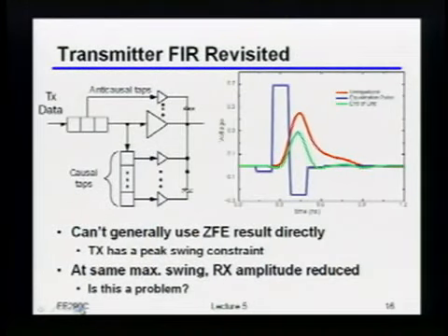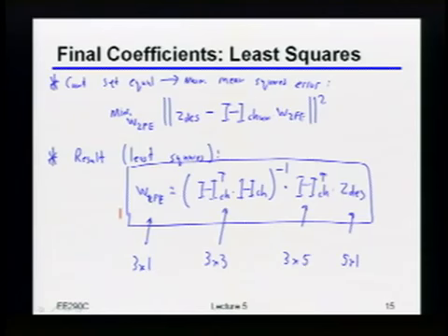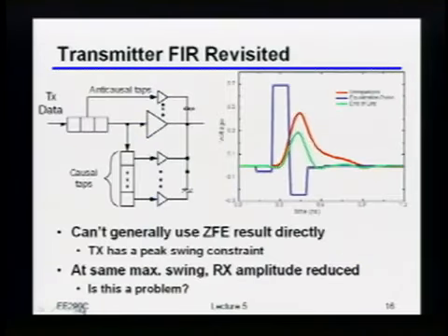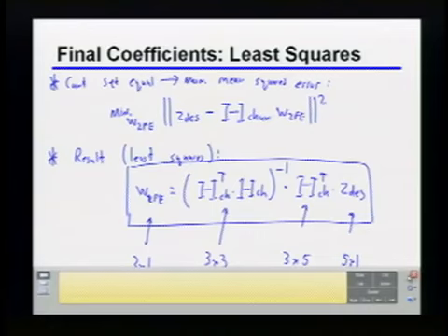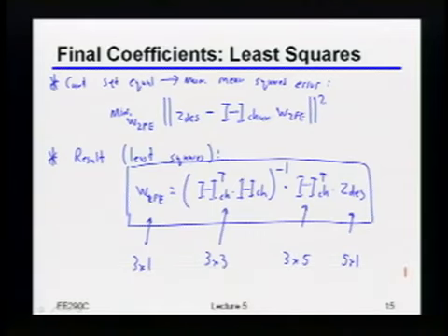Okay, great. Now that we got through most of the math, we can come back and take another intuitive look at this. The first thing I should mention is that if you plug this into MATLAB, which you will do, in general you can't take that result directly. The reason is the following. It will literally take whatever loss there was in the channel and try to compensate for it. If you had 20 dB of loss, this thing will try to put in 20 dB of gain so that if you had 1 volt at the input, you have 1 volt at the output.